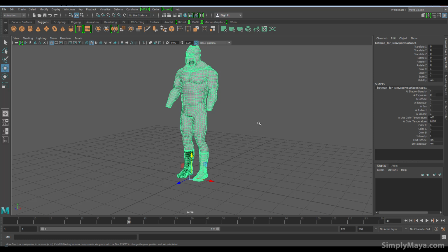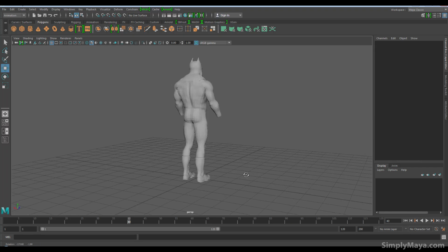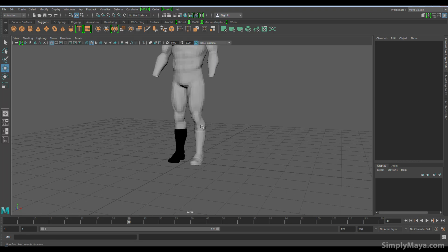I mean, it's not normally, but some simulation engines will take flipped normals as a sign that the surface is not solid and in fact pass through. So we're going to want to clean anything like that up. And if you're wondering how I'm seeing that, I'm sure Jay's told you this, I've got two-sided lighting turned on. If you have that turned off, you'll basically see this as normal, no defect. So you're going to want to go ahead, most of the time when you're modeling, and flip that on just to have a look around.